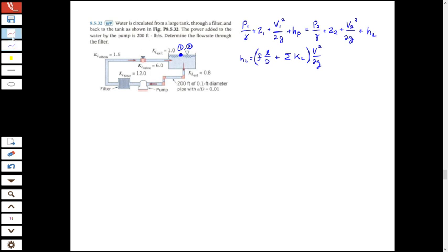And if it makes that loop, we can say that the pressures are 0, the velocities are 0, and the elevations are equal. So really, and it makes sense if you think about it, the pump effort needs to be equivalent to the losses of the system. In any of these circular systems, you're going to have a similar balance, where you need a pump that is sized appropriately for all the components of the system. That's using Bernoulli's to get to that conclusion.